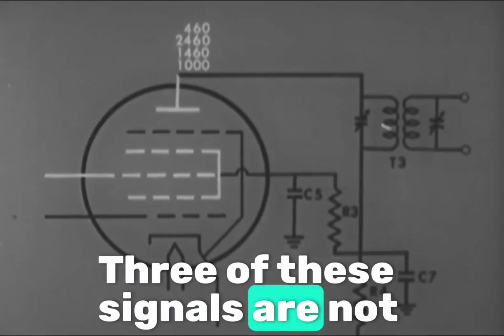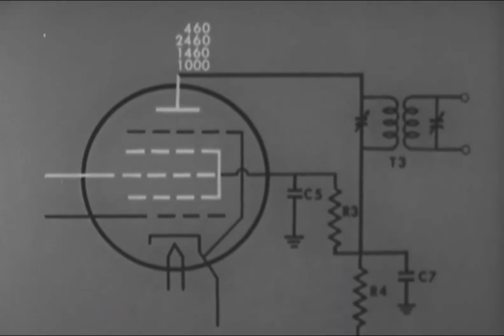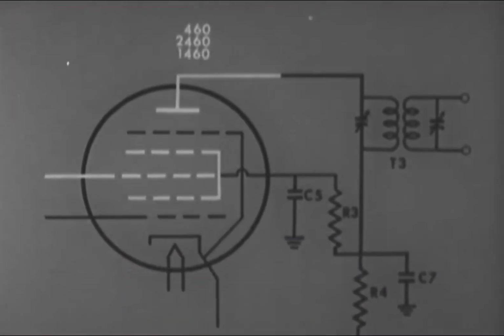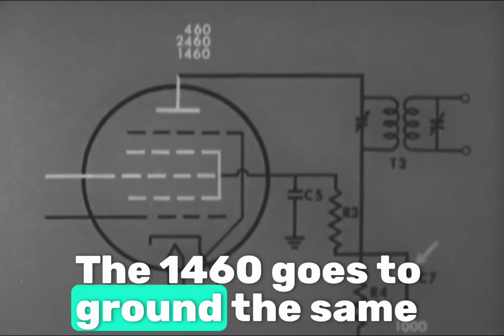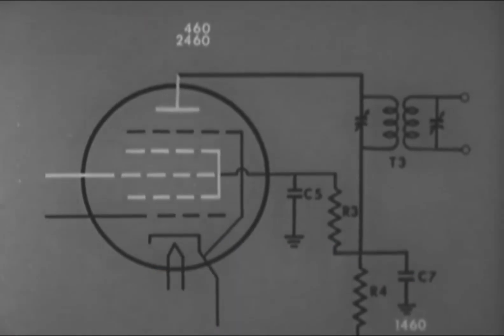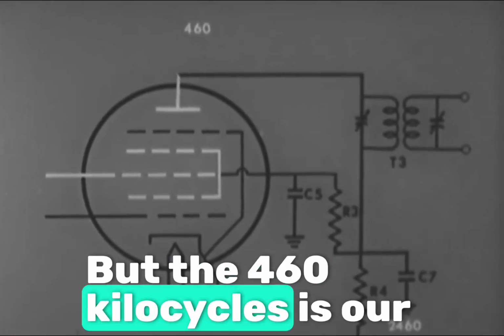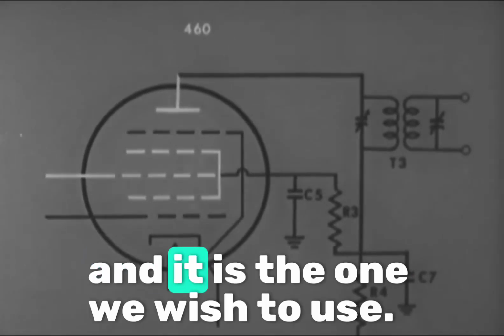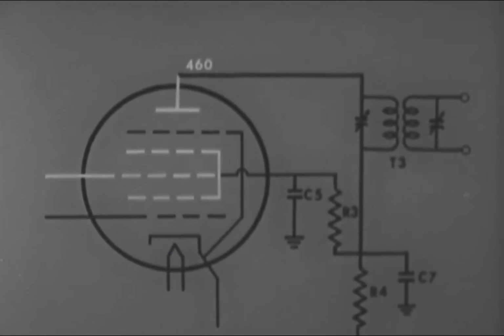3 of these signals are not required in the next stage. One of them is. The 1000 kilocycle signal goes to ground through this capacitor. The 1460 goes to ground the same way. The 2460 is lost in the same manner. But the 460 kilocycles is our intermediate, or IF frequency, and it is the one we wish to use.